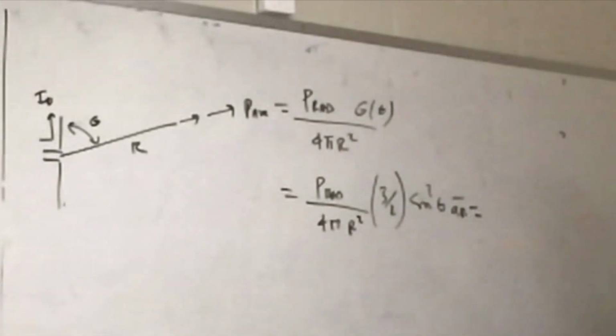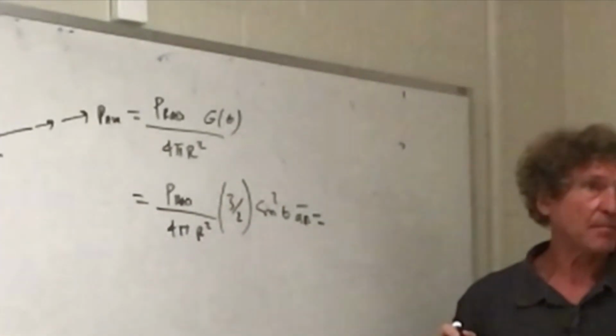Now suppose, and this is the nice way to do things in my opinion, we have the radiation resistance and we know the gain. If you could buy a commercial antenna, that information will be given. It's usually given from plots, because the antenna has a different amount of radiation resistance and reactance versus frequency. The gain slightly changes, so you can interpret this from the plots. The gain function does change, and a lot of times you're looking at the gain versus different frequencies in terms of the angle theta, and you pick out the angle you want the actual value at.